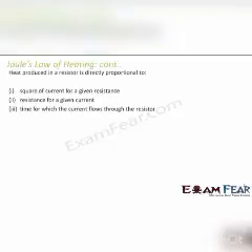So from Joule's law of heating, what did we conclude? We conclude that the heat produced in a resistor is directly proportional to the square of the current, because H is equal to I square RT. So it is directly proportional to the square of current. It is proportional to the value of resistance for a given current. It is directly proportional to the time for which the current flows through the resistor. So this also tells us that if current keeps on flowing through a circuit, the resistor gets heated up gradually, right? Because some amount of heat is getting produced across the resistor. So the resistor will get heated up in due course of time.